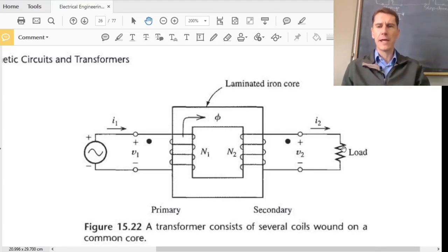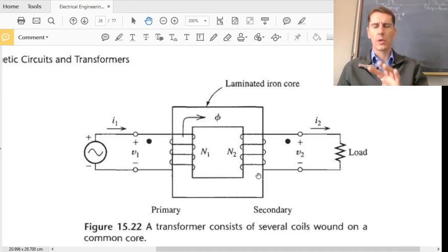Okay, now if we connect the load, then you've got a current that starts to flow. But now there's a bit of a snag here, because the moment that current flows in this coil, it's Lenz's law, it's going to oppose the change in flux. So the supply side coil, which we call the primary coil, primary is always supply side. As that flux flows through the secondary or the load side coil, secondary refers to load side.